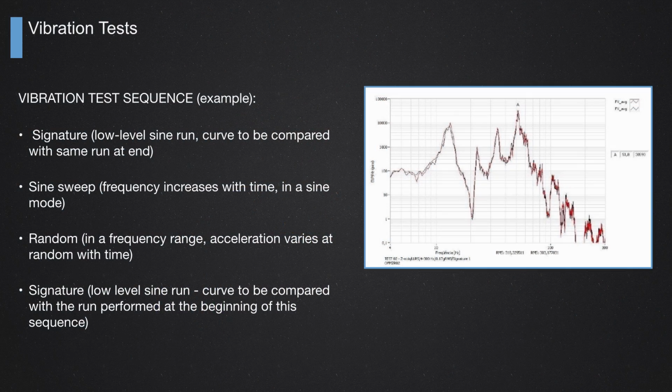And then we program the shaker with the vibration curve that the guys from the launch vehicle give us. They know exactly the level of vibration, the G's against the frequency. We have this curve, they give it to us, we program this in the computer, and we make it vibrate very close to what's going to vibrate during the launch phase. We put a margin, a little higher vibration, to make sure it's well tested in the laboratory here. That's the setup, that's the preparation for the test.